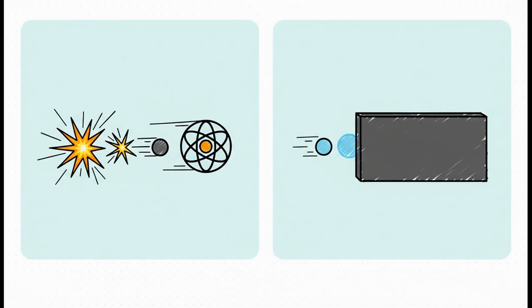The single biggest difference is the mechanism. We know avalanche breakdown is all about high-energy collisions. It's a physical process. Zener breakdown, though, is based on a mind-bending quantum mechanical effect called tunneling, where electrons can just pass right through a barrier they shouldn't be able to cross. Because the physics is different, the operating conditions are different. Avalanche breakdown usually happens above 5 or 6 volts in lightly doped materials, while Zener breakdown takes over at lower voltages in heavily doped materials.